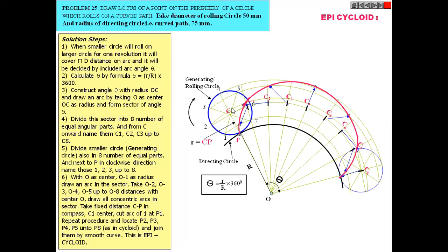So again, the possibility for this epicycloid is the same way as inferior trochoid and superior trochoid. Suppose this point P is somewhere inside the circumference, then the generated curve is an epitrochoid, but as it is available on the inside, it is known as inferior epitrochoid.